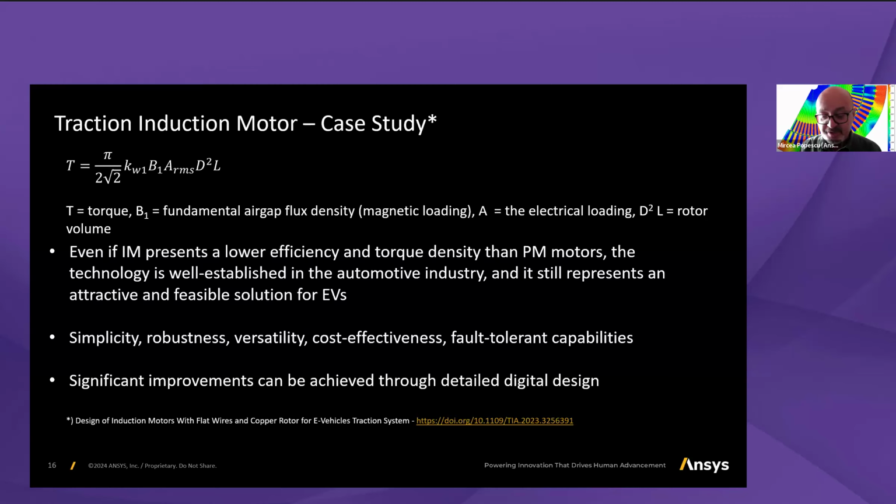This is what we guarantee. And then depending on the rotational speed that the machine will rotate, we can achieve a certain power. So therefore, it's essential to be able to go to torque level when designing the machine rather than power. So then it will give us a better understanding of the machine capabilities.